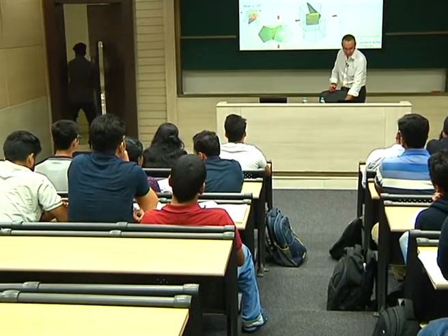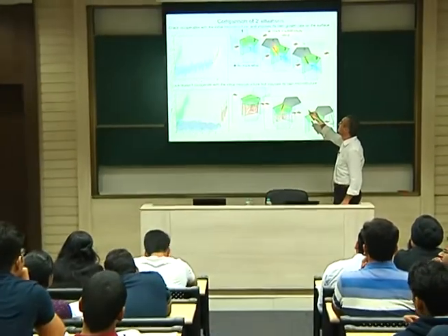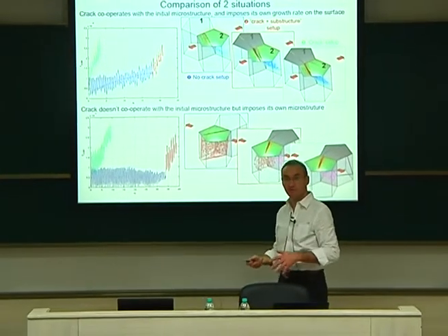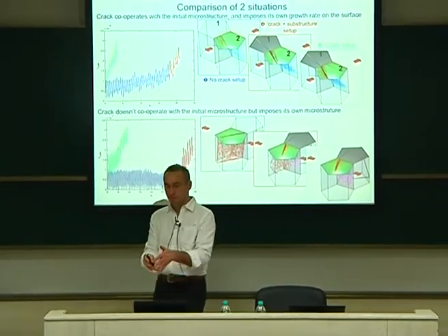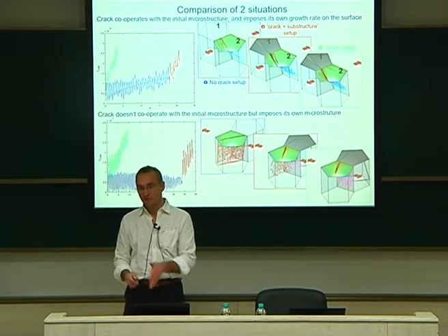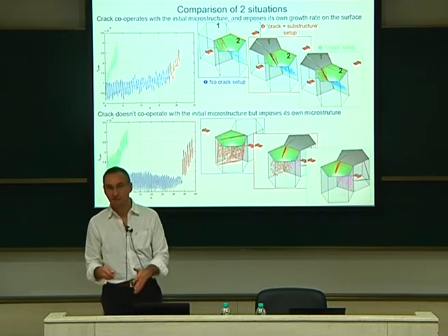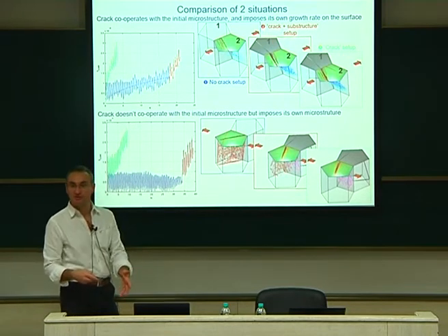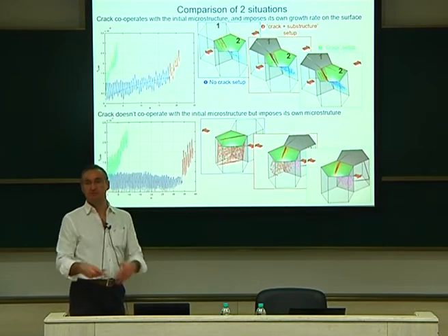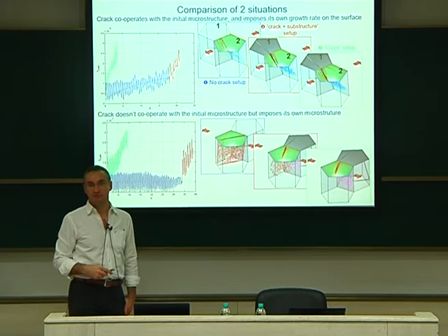Here we do the simulation without a crack, and we stop the code at that stage. Then we put a stress field corresponding to a crack. So we just add, at that moment, the stress due to the presence of a crack inside the simulation box. Be careful, the stress depends on the loading because it's plus and minus. You have some cycling effect because your stress tensor is cyclic. So it's not a constant stress, it's a cyclic stress, which is just increased by the sharp tip of the crack. We put the stress field at that stage and see what it gives on the structure.